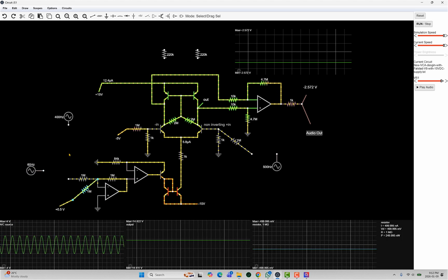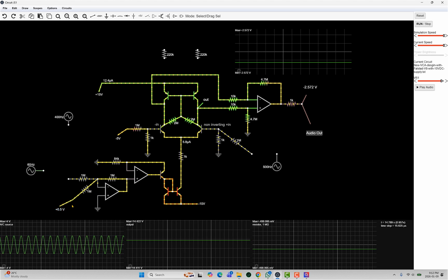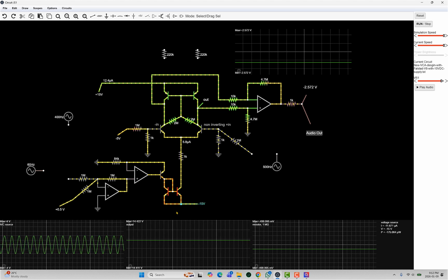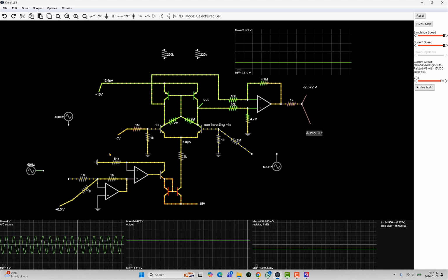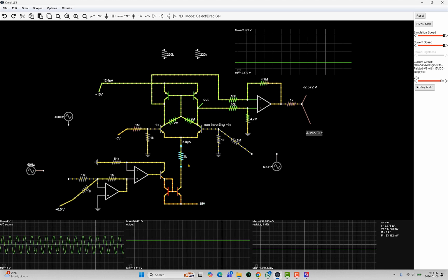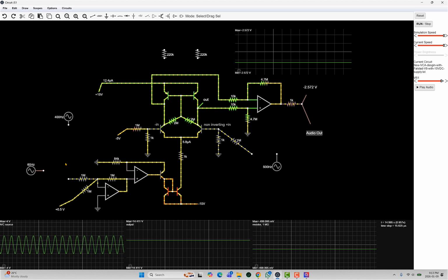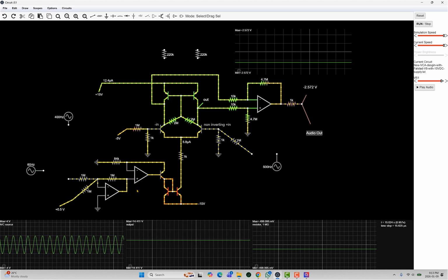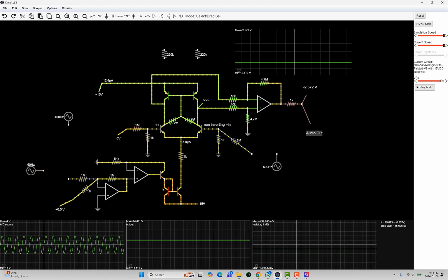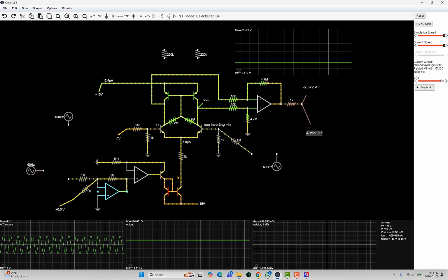And the way the amp works is this voltage is going through this circuit here. Okay, I'm just trying to outline it with my mouse. This circuit here is what they call a voltage to current converter, and it's linear. There are simpler ones, but this one's linear. So if I double the voltage, my current should double, or if I halve it, it should halve.